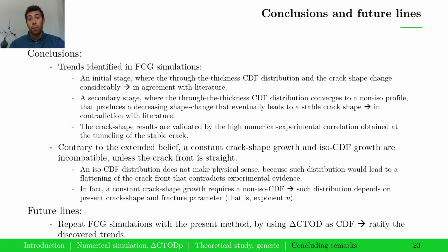So the remaining work, in view of the potential of the methodology, is to repeat the fatigue crack growth simulations with the total crack tip opening displacement range and see if we ratify the discovered trends.